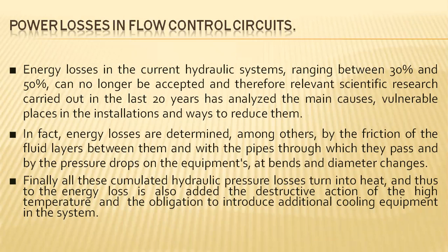Power loss is nothing but the directional changes or crossing at different elbow levels, or directional changes at the control valves, and even the diversions of fluid from one alignment to another, and shifting of the fluid by passing through the pressure relief valves and directional control valves, and then finally reaching the actuators, leads to minute losses of pressure within the fluid.